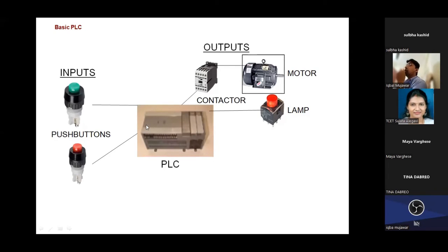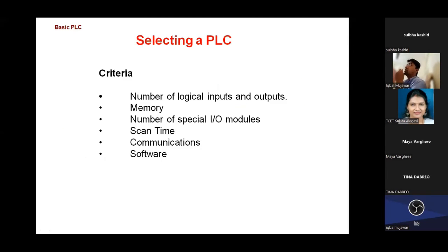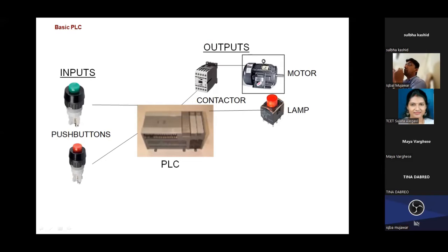But as I said previously, when you are connecting devices to the PLC, I need to look at the addresses also. That is a very important part, because in ladder coding I need to specify the logic and the addresses. We mostly use only 3 symbols: normally open contact, normally closed contact and output coil.